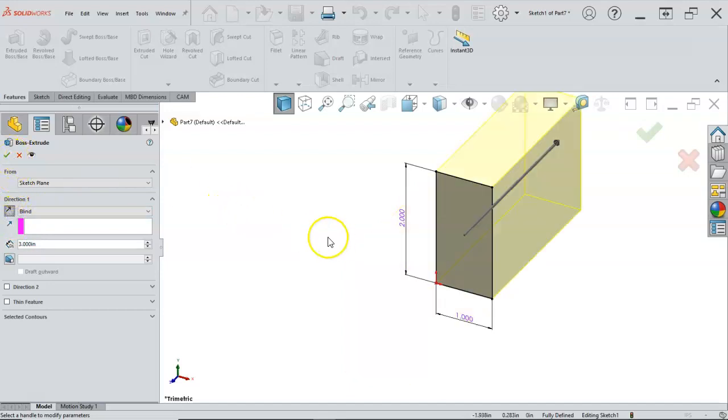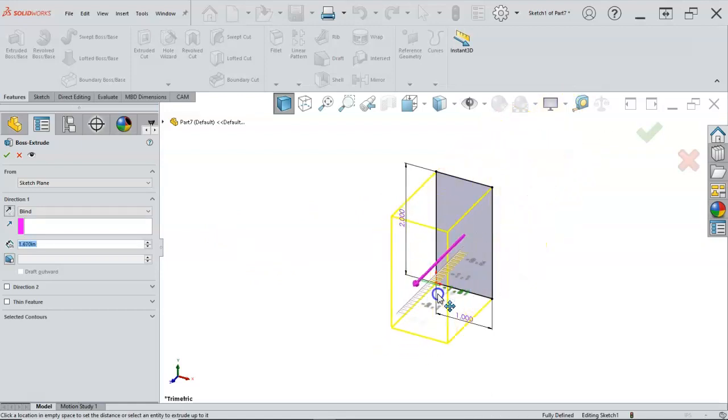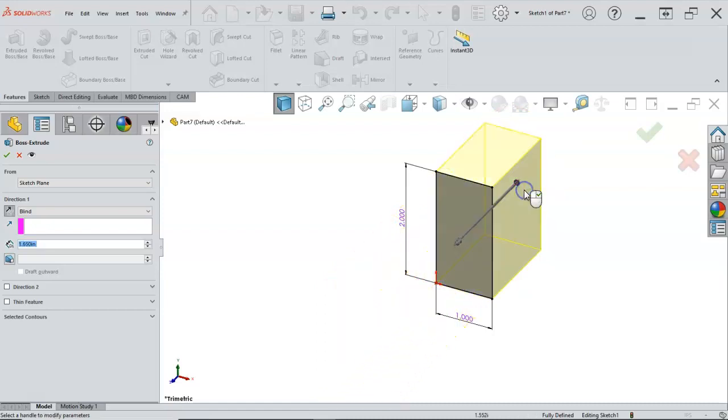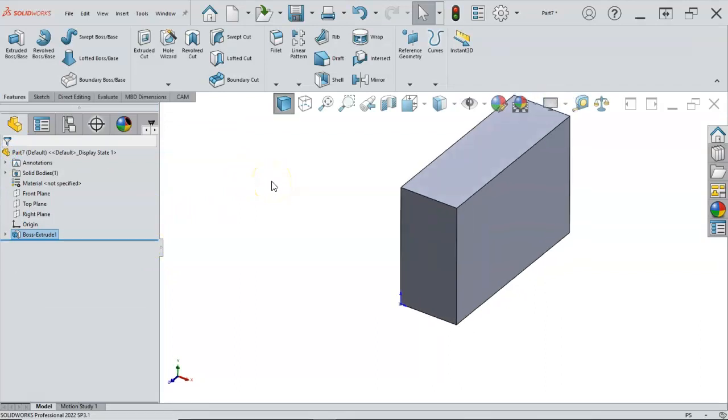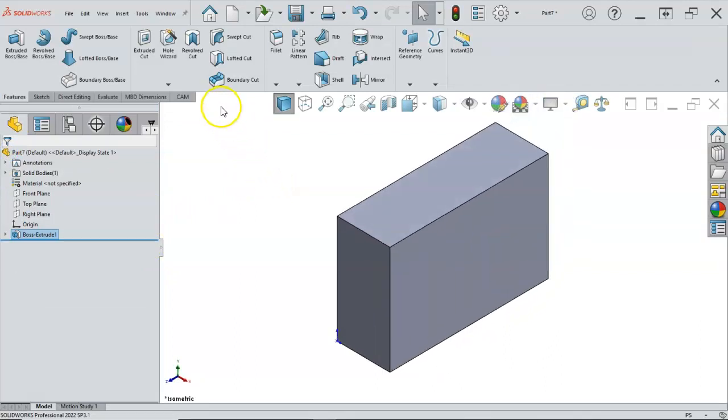All right, and then I'm still going to tell you to stay away from parameters in the sketch. Also with the arrow and the ruler, you can get pretty close, but that's kind of time consuming to do that for every part. It's a lot easier just to get it close, enter the value, and say go. All right, so Control 7 will kind of center it.